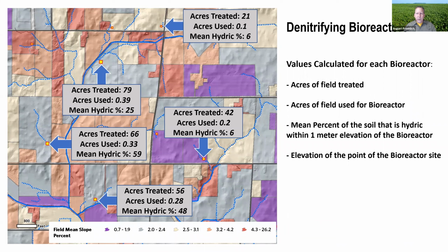the process that's used in doing this is pretty neat, but the first step is to identify the lowest point in the whole field. Then make sure that it's the lowest point heading out, that water is actually draining at the outset, or it is the lowest point where water is leaving the field.